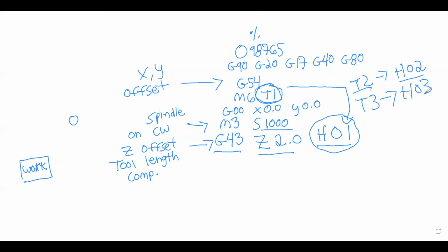We're going to be installing them into the spindle, moving them down with the hand dial, touching them off to the top of our workpiece, and the length of hangout of each tool will almost certainly be different per each tool.